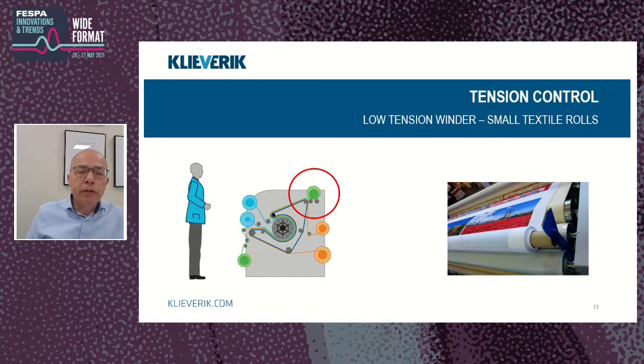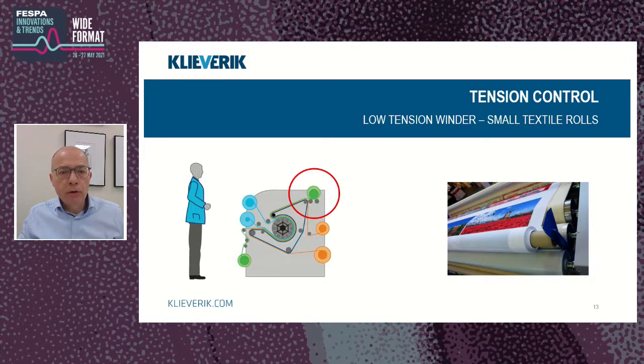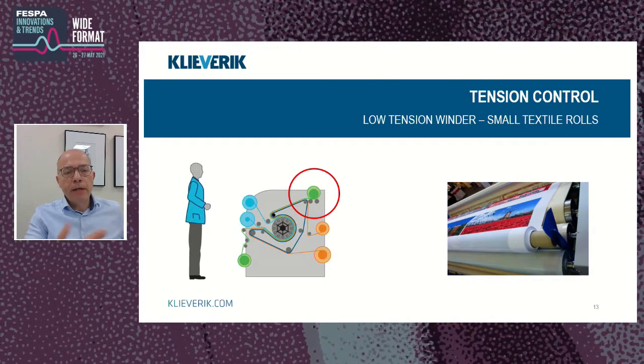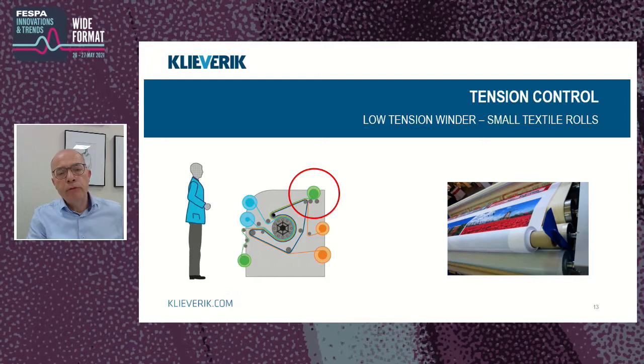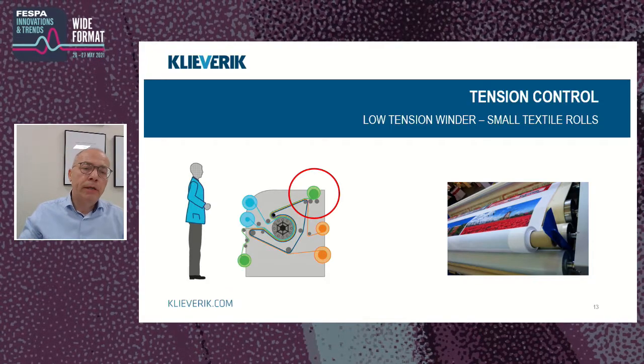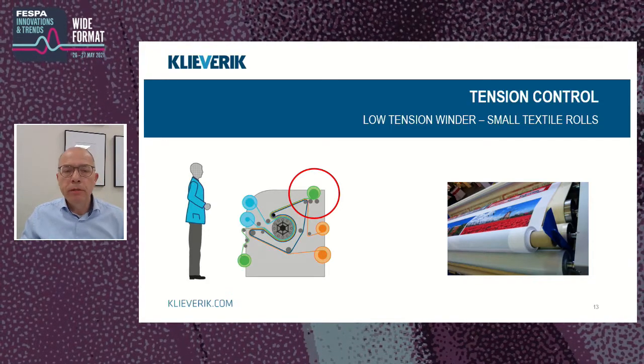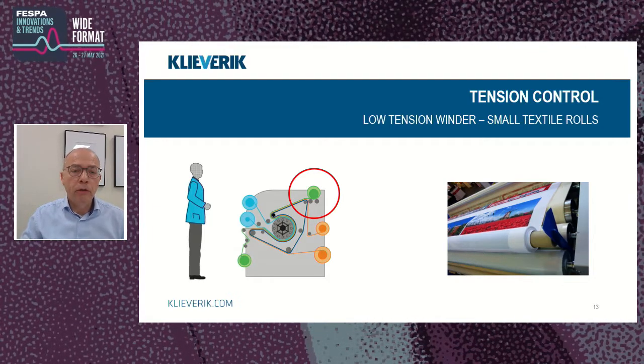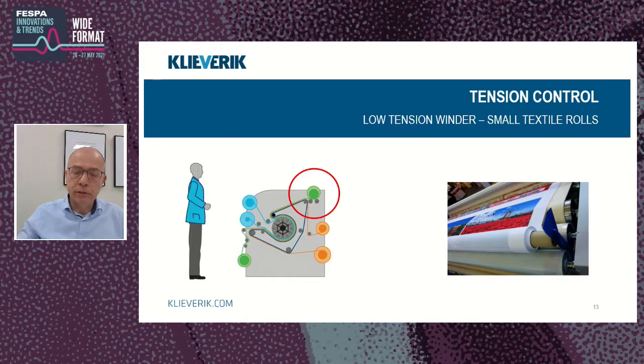Now, the nice thing about the contact winder, to mention alongside as well, is that you're not winding on a shaft. That means that whilst you're processing, you can take the first meters off, take it to the cutting machine. Machine is continuing processing, and you can continue winding on the new core. Very nice feature integrated in that.